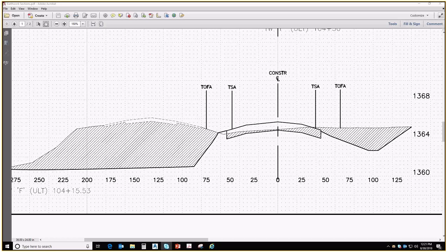The first step is to sit down with your cross-sections and your final design, whether it's a roadway alignment, a taxiway alignment, or a site grading plan, and pick some spots on your design plan for elevations. Then go to your cross-section at a similar place and make sure the finish grade in the cross-section matches the finish grade on your design. That's a very simple check, but that's exactly what busted on the project I was telling you about. We made a final last-minute change, and it didn't get reflected in the model, so even though the sections looked right, they weren't actually at the right elevation. So that's the first check.